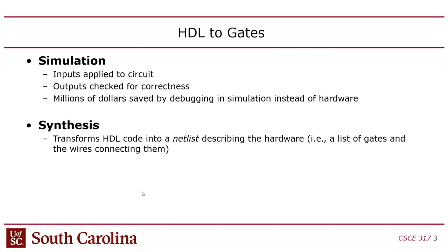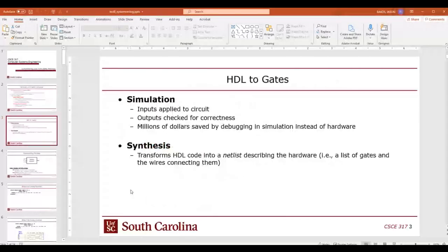So anyway, I mentioned that there's simulation, which is where you write your code and you test it. You simulate it like simulating a logic circuit, like you do with SPICE, except SPICE is a circuit simulator, not a logic simulator. So when you simulate HDL code, it's with a logic simulator where everything is binary as opposed to analog voltage values. And then synthesis, as I mentioned, is when you kind of compile the code and convert the high-level code to logic gates and wires, basically to a schematic, a hardware schematic.